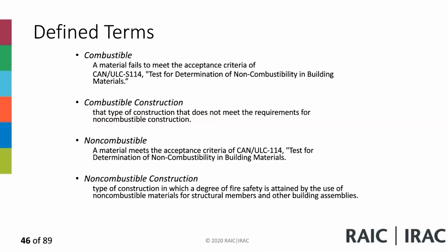So you have paint, self-adhesive tapes, mastics, caulking materials, plastic air sealants for use in exterior walls, fire stops or fire blocks as conforming to Sentences 3.1.9.1 and 3.1.11.7, tubings, electrical outlets and junction boxes, adhesive paper barrier, shielding papers. So get familiarized with the provisions and the articles related to combustible components and materials that are permitted in non-combustible construction.